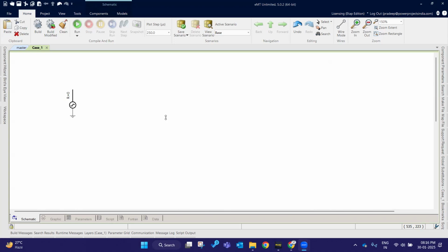For each and every component, we should validate something, and only then place that component in our main SLD. For that validation purpose, we should create another file and do the validations there. If the model is validated and perfect for use, only then should we copy it and place it here.